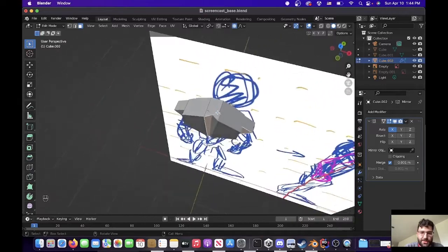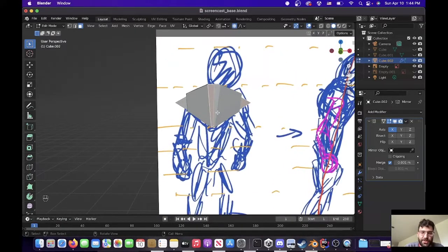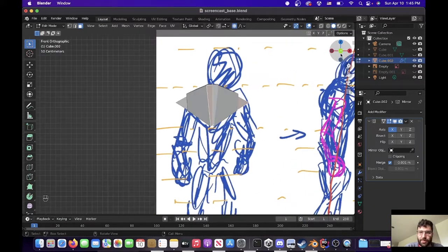And you'll notice it's kind of screwy. It's a little bit weird because we have parts of our mesh, there's this line of symmetry that goes up and down. Parts of the mesh are overlapping that line of symmetry, which means it's going to get double folded, which is all kinds of weird. If you hit clip, some of that goes away, but notice over here where it says axis, you can choose to have symmetry in different directions, or even across multiple axes, but we just want x-axis symmetry up and down.